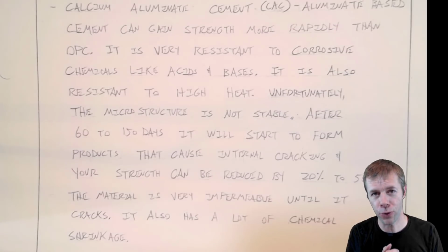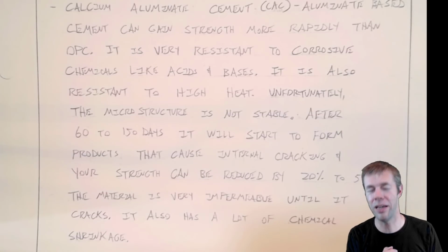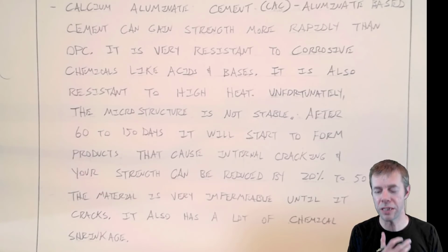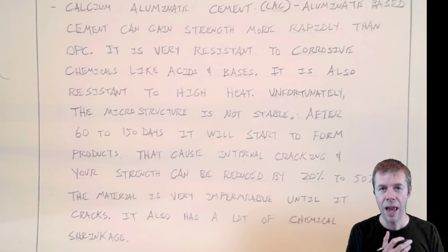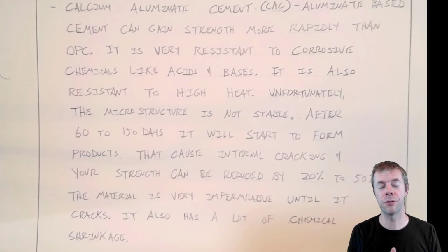But then you get to another 28 days and you lost 20% of the strength. And you get to another 28 days and you've lost 50% of your ultimate strength. Yikes. This can be bad. If you don't understand this, this can be extremely dangerous. And this material has caused several structural failures because engineers didn't understand this strength loss.